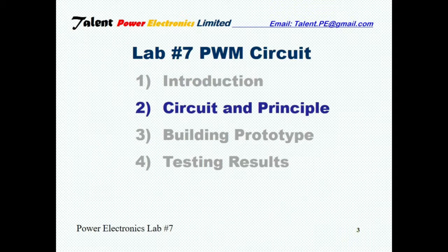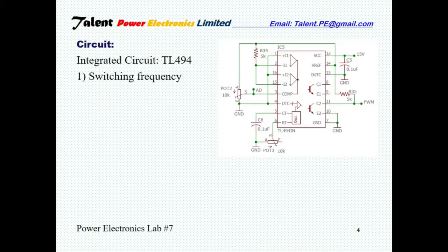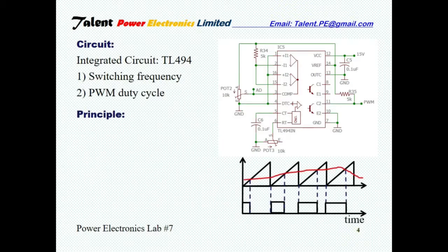Now let's look at the circuit of the prototype and its working principle. A pre-designed integrated circuit, TL494, is used in the prototype. It will output a PWM signal and control the two features: 1. Switching frequency, 2. Duty cycle. Here is the working principle of the prototype.